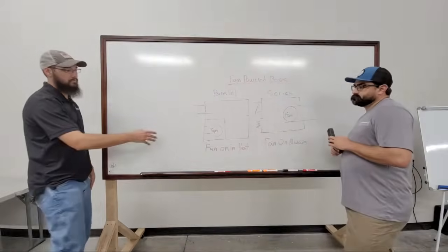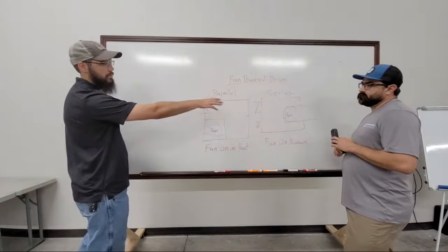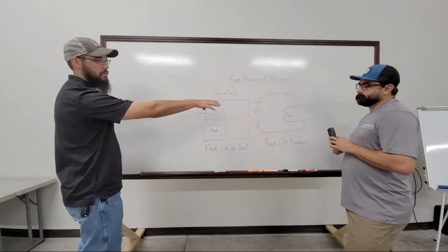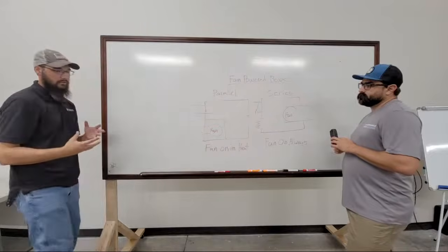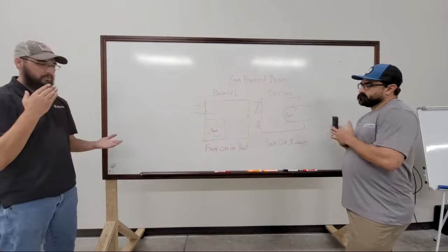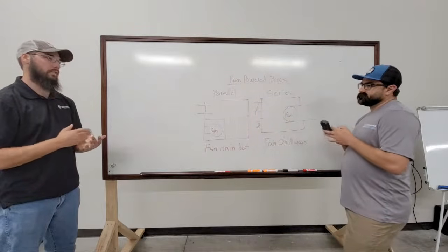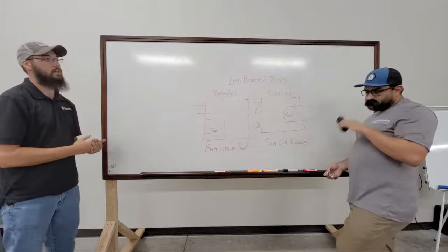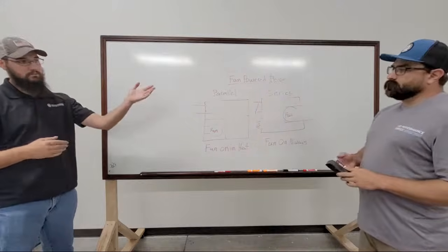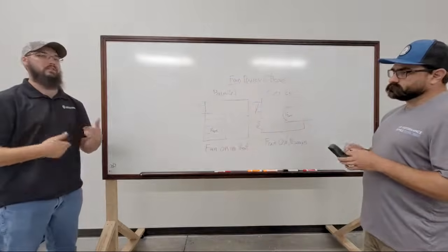Well, that and almost the vast majority, this will be a PSC motor versus ECM. So where that'll ramp itself up, any kind of electric motor, I think it's like 80% of the wear and tear on that motor is the start and stop. Yeah. Specifically the start, because of the inrush current. Having it modulate up reduces that wear, but it is still wear having to get started.